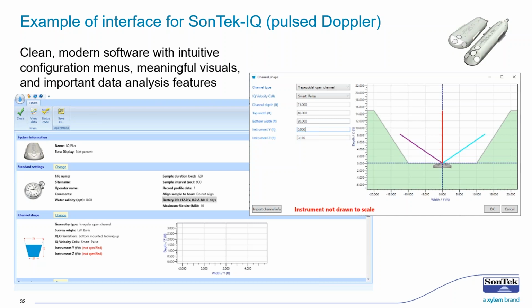Because remember, these instruments output a velocity. That's the real measurement, and flow, or discharge, is a calculated parameter, or total volume is a calculated parameter. So the instruments can measure velocity pretty darn accurately, but that calculation, that flow number, depends on the user. So if this channel geometry isn't precisely programmed or known, then you're introducing error in essence. So that's another source, that's a slop factor that I think people encounter, that once you're aware of it, you can do something about it.